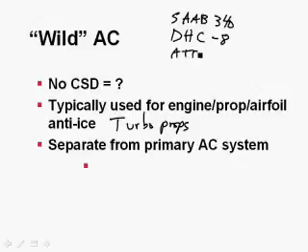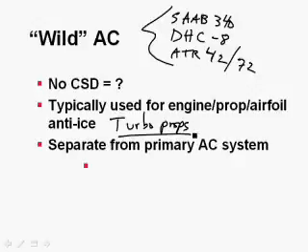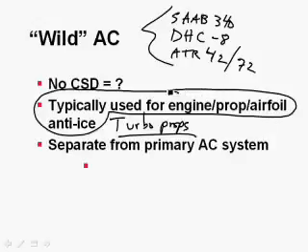Oh yeah, the ATR 42 and 72. And in all cases, these are big ol' honkin' turboprops that primarily have AC systems, but they put an extra AC generator out on the propeller reduction gearbox, and they drive an AC generator, but then they only use it for heating purposes, to heat the engine inlet anti-ice, to heat the hot props, to heat some hot airfoils on the wings, to keep ice from sticking on it.